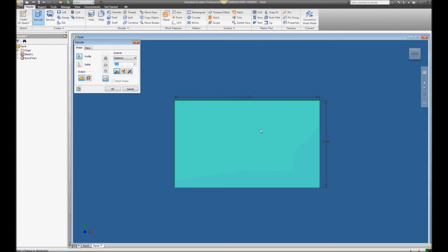Let's extrude it. We need to select our profile and our distance, which is going to be our plate thickness, D2. D2, for geometric relationship, says that it is 20 times smaller than the overall plate width. Now we're going to find out what overall plate width was. We just did it. It was D1. So we're going to type in D1, and it's 20 times smaller than D1, so we're just going to divide it by 20. We're going to drop that in.